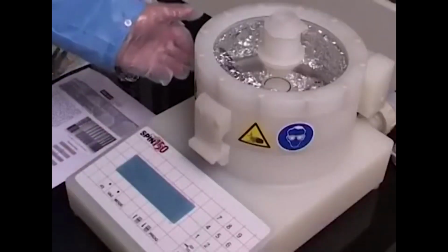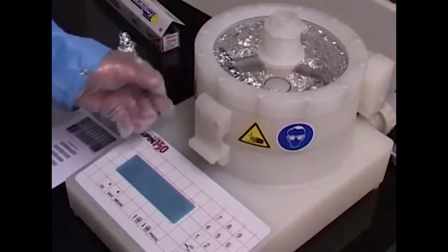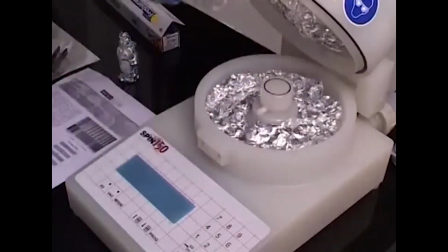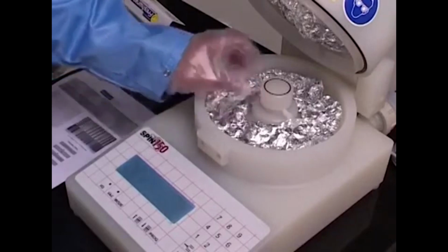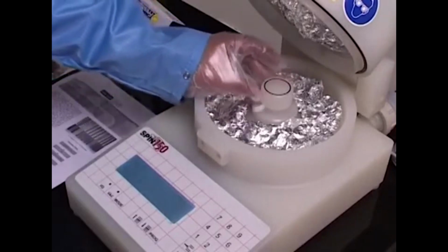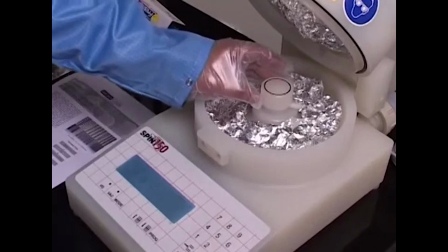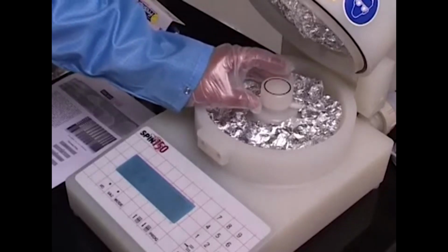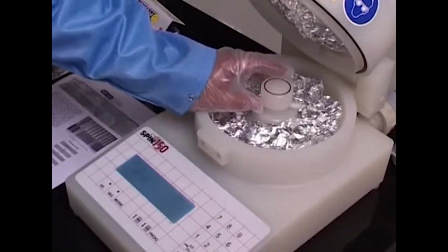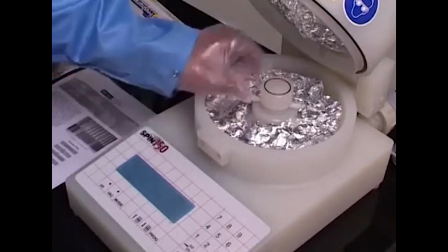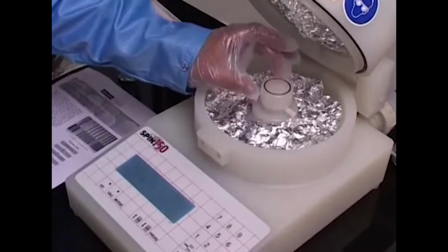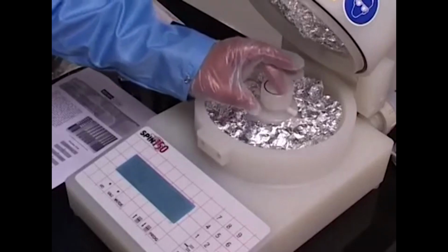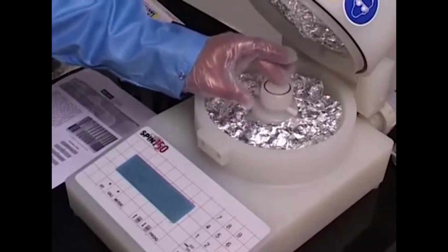This right here is what we call the spin coater. Essentially, if you look into this machine closely, you have a spin stage which is represented here, in this area. Essentially the principle is you use vacuum for holding the wafer onto the spin table, and if you look closely into this particular area, you have these grooves which are crisscross, and they are placed over the whole periphery of the spin stage.